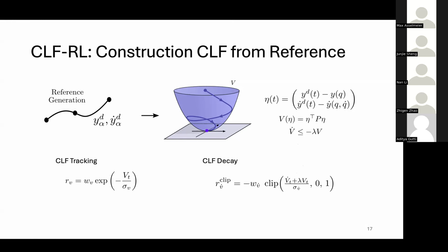The other one you could do would be the pelvis position and all the end effector positions and orientations. It also included the velocities of all of these things as well. So the Lyapunov function encodes both position and velocity tracking, and then the decreasing condition has us decrease to this. So in some sense, the V dot term is on velocities and accelerations.